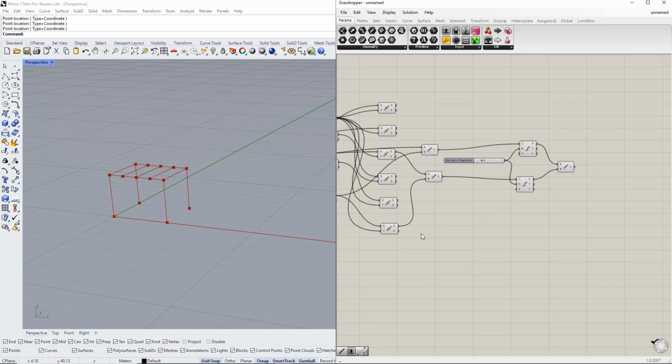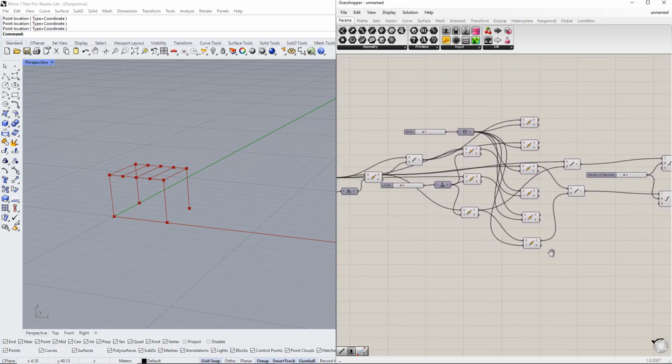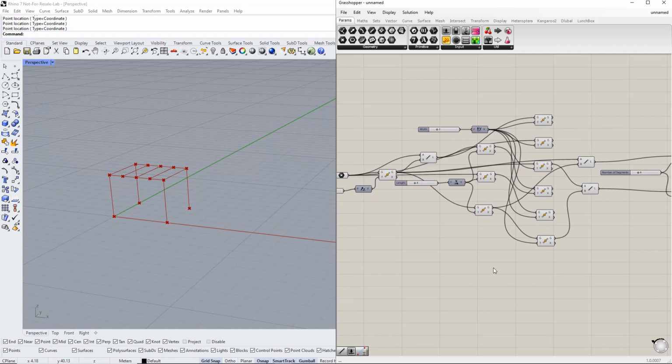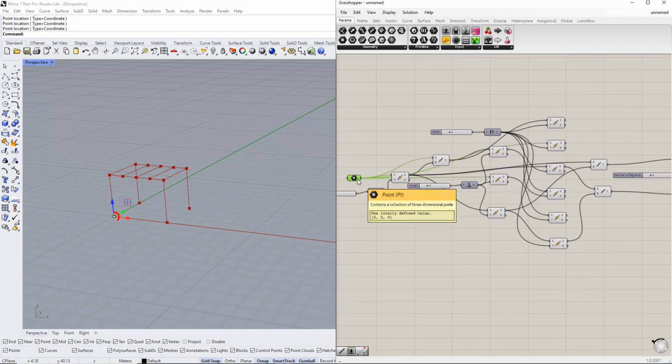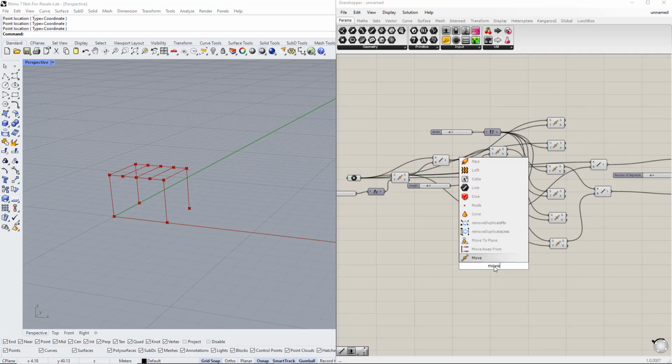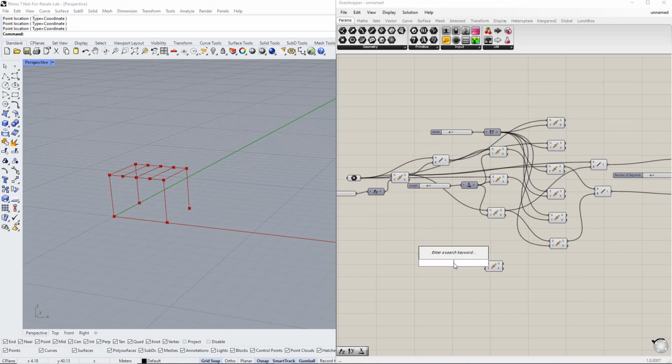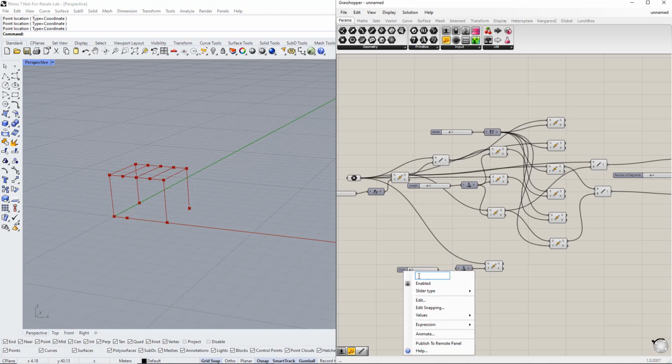In the next step, we create lines for struts. To do this, we need to copy the 2 points that are parallel to the y-axis in the x direction using the Move component. We also insert the unit vector parallel to the x-axis. After that, we set up a new range, for example, from 0 to 5. We enter distance for this slider name.